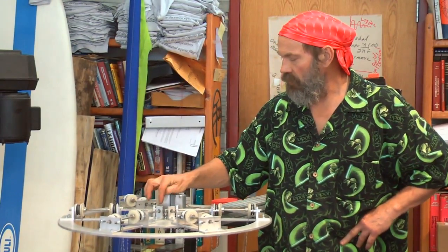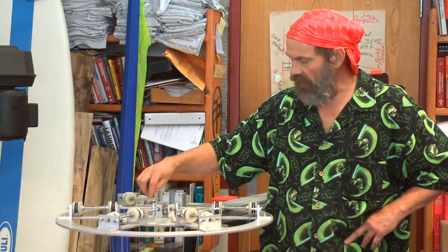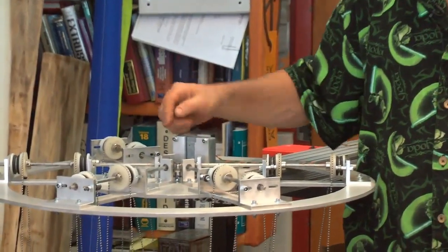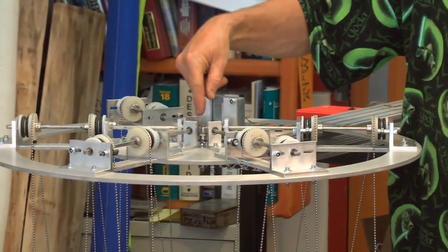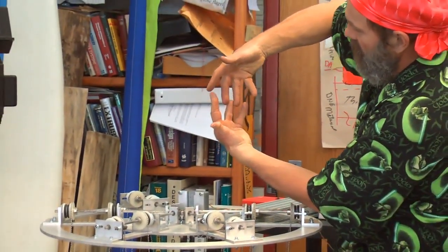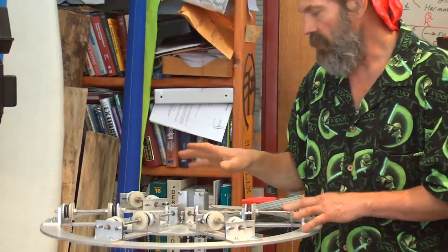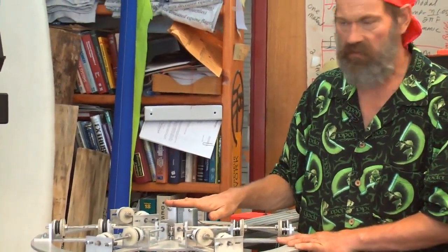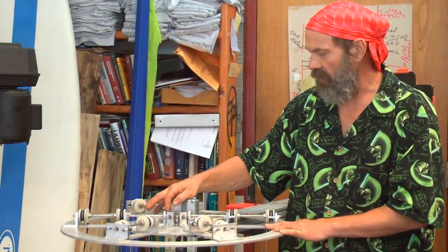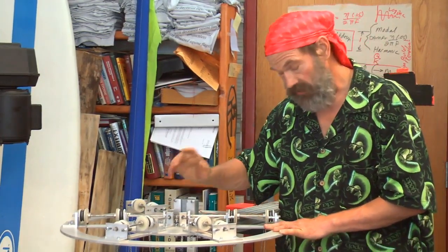In that the loads on this device are very small and the shaft deflections are very low, but if the gear really had to transmit a lot of torque, the shafts would start bending up and either the teeth would start skipping, or instead of running at the proper best contact zone, the teeth would start running near their tips and they would wear out much more quickly. So even though the design looks wonderful, if you go to actually implement this in reality, you'd want to have this front support bearings here located up real tight, right close up to the back side of the gear face, the teeth face.